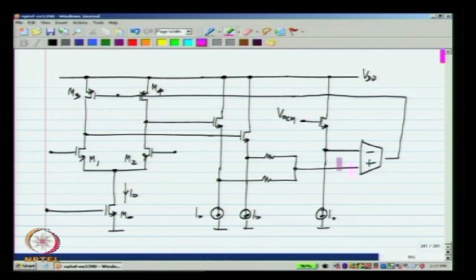Now, in this case, when the common mode feedback loop works properly, the common mode of these two voltages will be set to VOCM. MC11, MC12 and this MC11 prime are identical to each other. And we have this RCM and RCM here, and we usually also have to have these capacitors CCM to make sure that there is not too much delay in the common mode feedback loop.